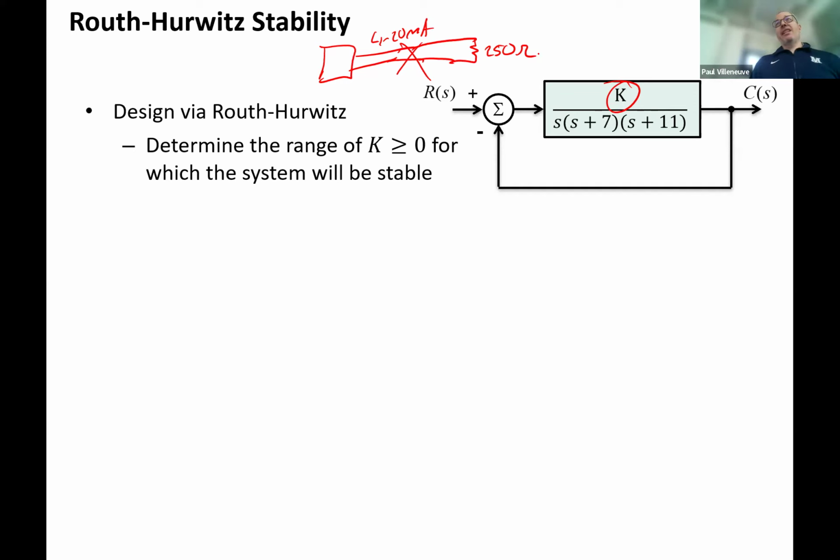But a lot of stuff, like I said, is now transitioning to fiber. You could even use wireless, but the problem with wireless is it's not the most robust. Even if you have a very reliable wireless system, you can still have people hack you, and you can still introduce noise. For any process control I've seen, though I'm going back a few years, it always wants a hardwired input signal.